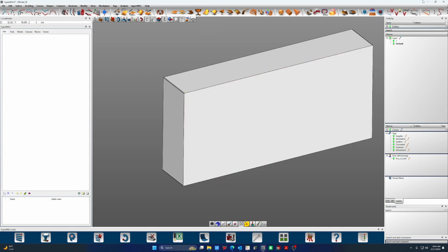VSketch toolbar. VSketches are our newer addition to hyperMILL. V-sketching is parametric sketching inside of hyperMILL. So we're driving lines based on parameters. So when we modify those parameters, we can make a net change in our shape, just like in SolidWorks or NX. If you model something 10 by 10, you create your solid, you're 20 steps down the line, you go back and make it 12 by 12, it's going to update the solid model you created and everything thereafter.